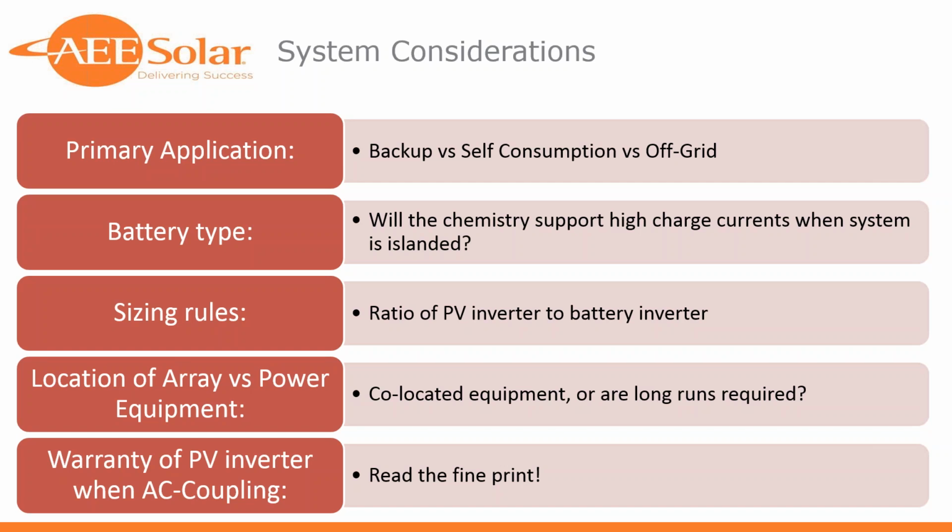Next consideration is location of array versus power equipment. Is it co-located? Are you within short distances, or are long runs required? As we talked about, if you're dealing with long runs, you really might want to reach for that AC coupled tool in your toolbox.